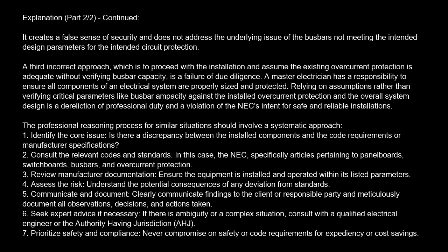A third incorrect approach, which is to proceed with the installation and assume the existing overcurrent protection is adequate without verifying busbar capacity, is a failure of due diligence. A master electrician has a responsibility to ensure all components of an electrical system are properly sized and protected.